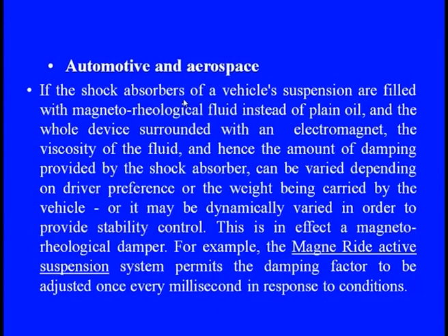And also, we can say that for providing stability control, these MR dampers are perfect. So, this is an effect of the magneto-rheological damper, for which a magneride active suspension system can be adopted, through which the damping factor can be adjusted every millisecond in response to the condition. So, they are so quick in their response.